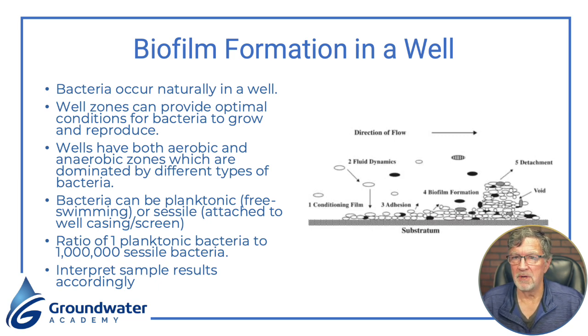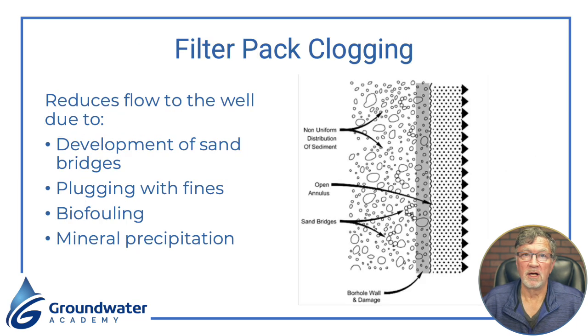So you've got to keep that in mind when you're interpreting your results. Also, iron and manganese bacteria can form slimes, and sulfur-related bacteria can grow underneath those slimes. So you actually get a consortium of bacteria growing in your well, and that's important to understand.